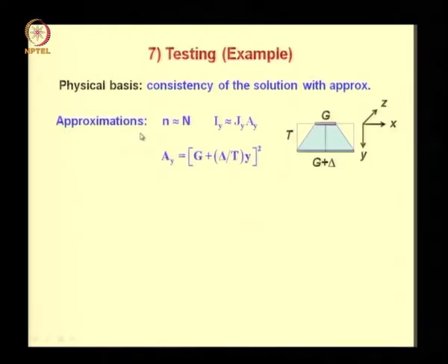The approximations we have made are space charge neutrality, which implies that the electron concentration is approximately equal to the doping concentration. Then the current at any y, so here is the y direction. When I say current at any y, it means that current over the horizontal area of cross section of this pyramidal current flow, that is given by Jy into Ay, where Jy is the assumed approximately uniform current density over Ay.